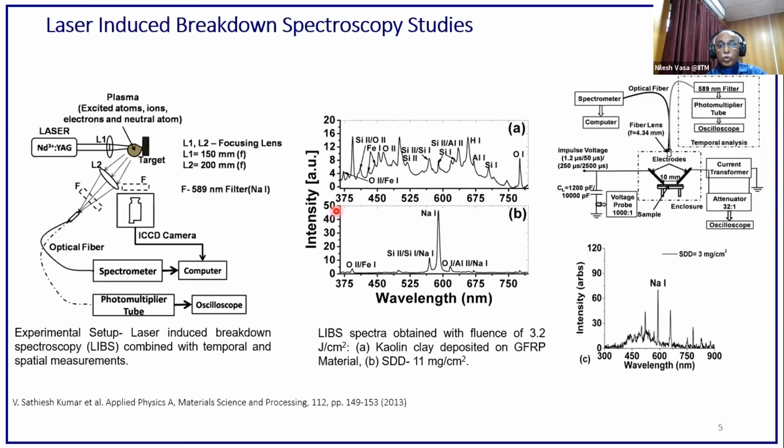And in parallel, we also studied electrical discharge in order to realize how the dielectric strength or the material characteristics are getting degraded from the electrical point of view because of the salt deposit, and with various concentrations of the salt deposit, how the surface characteristics are getting deteriorated.